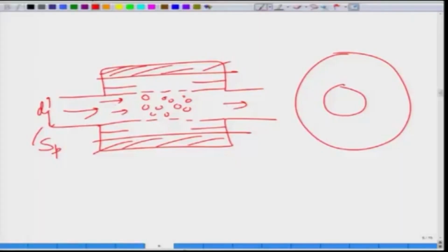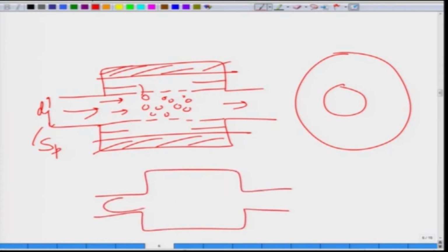So, a smaller duct has more impedance towards, or it offers more opposition to, the propagation of acoustic waves, and we will see that the moment we use things like this sudden expansion that is happening here partly, or maybe things like this, the impedance of this port and this port, while they are same, the characteristic impedance of this part is vastly different from this one. So, this will be one of the reasons why a lot of acoustic power is reflected back into the system, and why that attenuation is being produced.